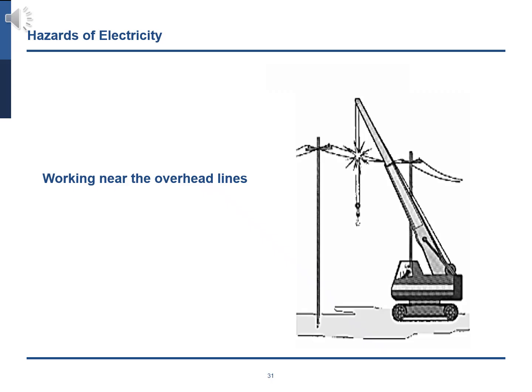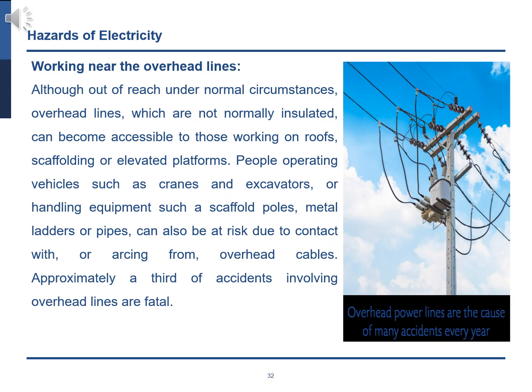Working near the overhead lines. Although out of reach under normal circumstances, overhead lines, which are not normally insulated, can become accessible to those working on roofs, scaffolding, or elevated platforms.